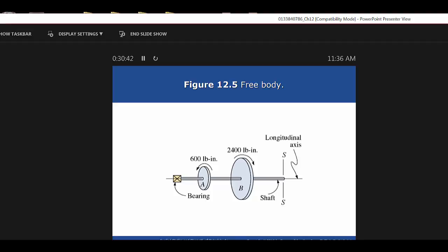But to make it all one, that kind of sucks. Or maybe the pulleys aren't set up like that, that you're trying to buy. They'll have different diameters, so you have to make sure that the internal diameter on a pulley that you wanted to slide onto a shaft would still allow you to create a shaft big enough for that. Varying speeds. Do what? You need different speeds coming off.